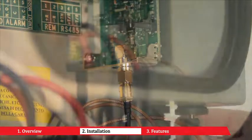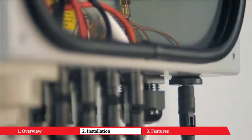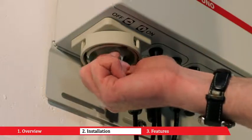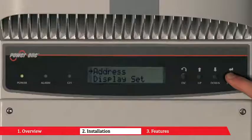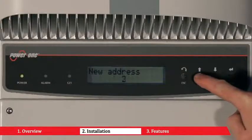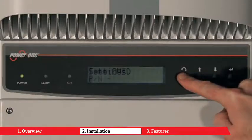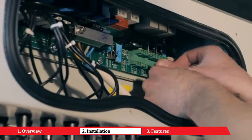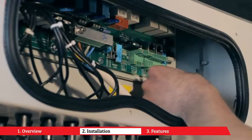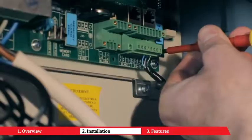Check that the PVI radio module is correctly installed. See the PVI radio module manual to initialize radio communication. Check that the Aurora inverters in your photovoltaic or wind plant are turned on. Check that the addresses for the RS485 ports are all different. They do not need to be sequential. Check that the current date and time is set on the inverters. Check that the RS485 wiring is correct and inserted if you want to initialize RS485 wired communication.